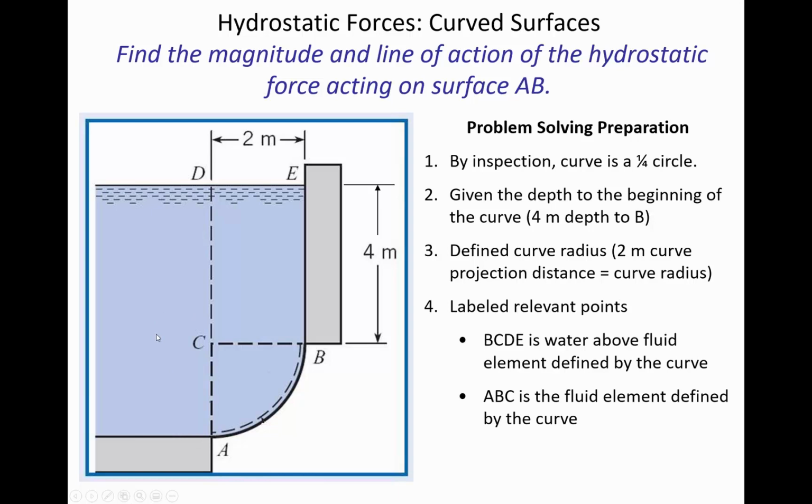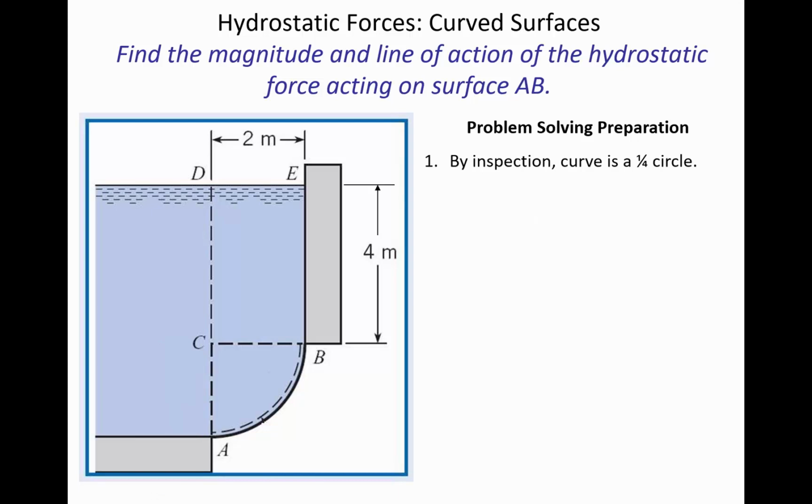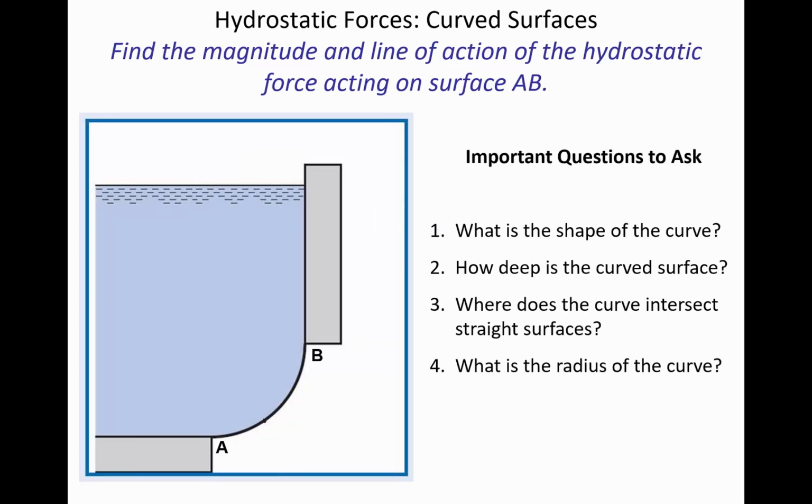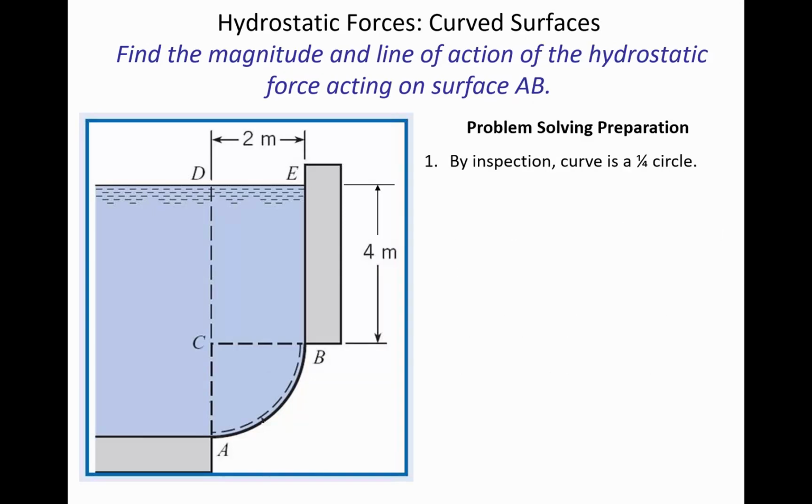And then it's helpful even if the drawing doesn't have points labeled. Like if this was the original drawing that you were given, it might be useful to sketch out what is the shape of what's above that gate. And so to sketch out the quarter circle, to sketch the rectangle that's above the gate, because those shapes are going to have to be accounted for because there's a certain weight of water above the gate.